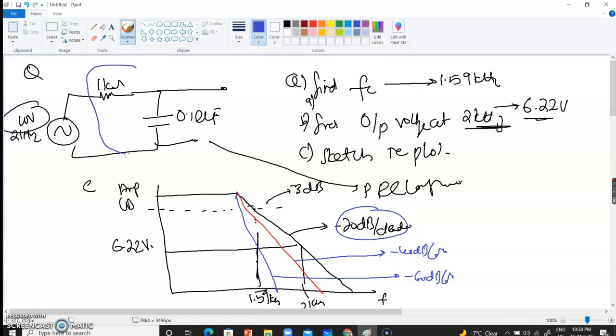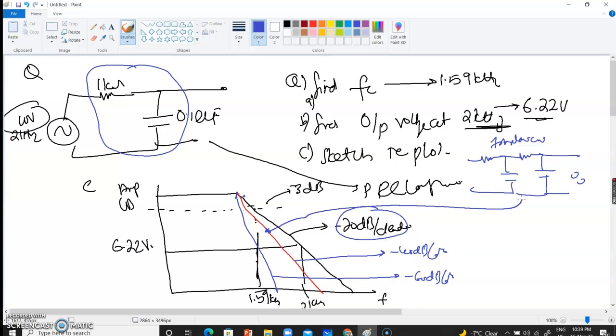This circuit over here is just an RC circuit with one resistor and a capacitor, which is a first order circuit. If I increase the order to order 2, right, and then take the output, then I can make the slope steeper and make this a sharp filter. So this will now be my second order circuit, which has a slope of minus 40 dB per decade. So as soon as we increase the order of the circuit, the roll-off becomes steeper, and you can design such a filter which is very steep in nature so that your design requirements are fulfilled.